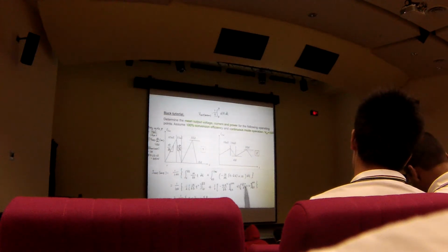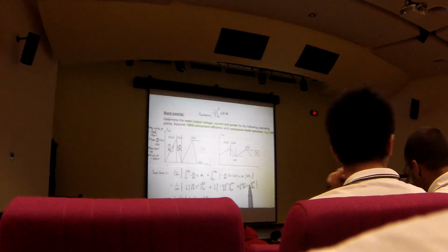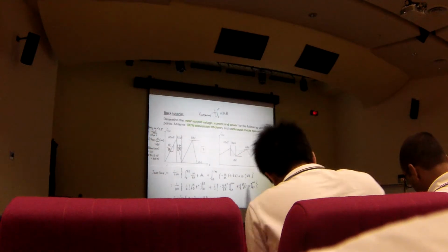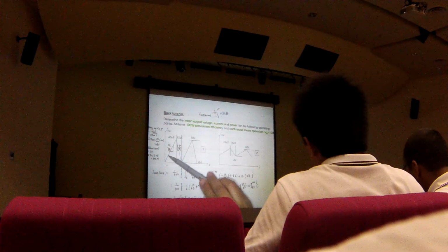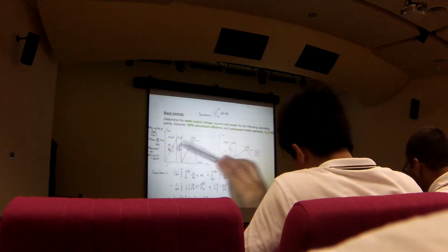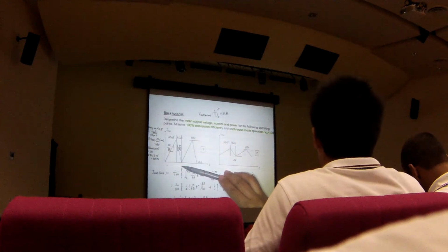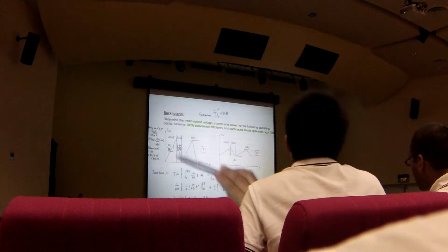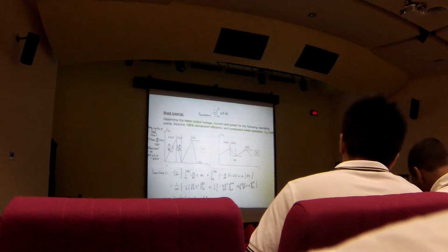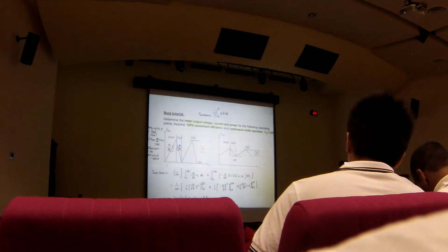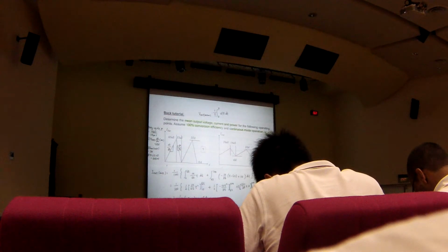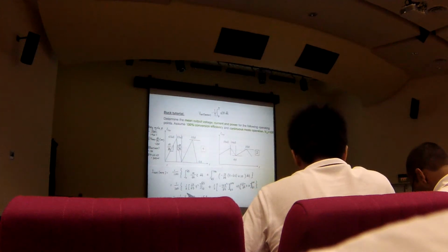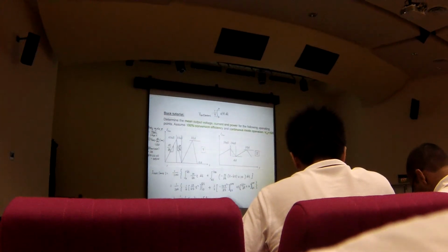You have to be able to do this. Given any arbitrary waveform, if they ask you for the rate of change, the peak to peak value, calculate the average and calculate the root mean square, you must be able to do all this. If you integrate t, you get t squared over 2, and you substitute the corresponding values.